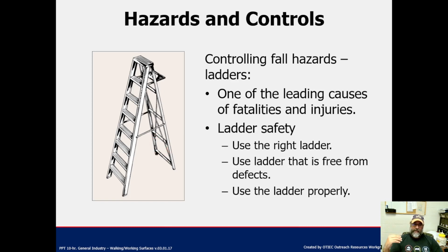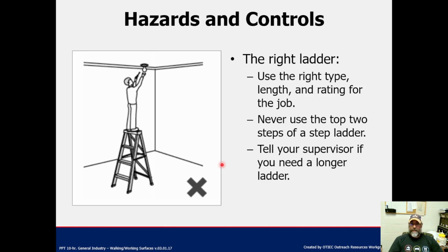So, things to take into consideration. The other thing is that you'll see it on all ladders. They tell you never use the top two steps of a ladder. The reason is, when you're standing with the top two steps above you, you can lean against something. When you're standing on this tiny little area up here, there is that major potential for falling off the ladder. Use the right ladder for the job.